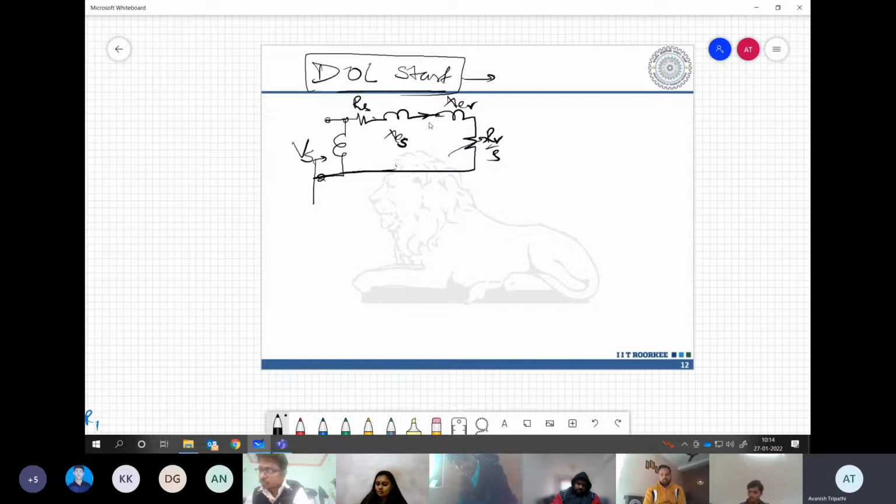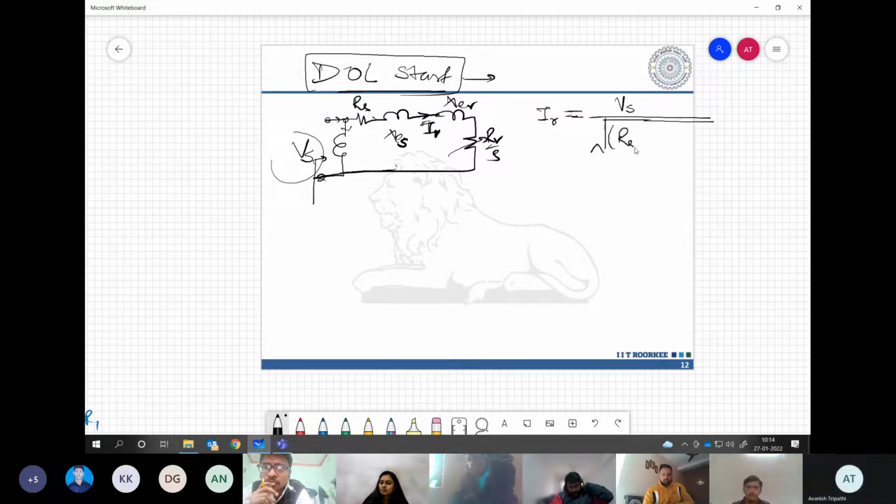Now the rotor current is more or less the stator current. That's what we know because the magnetizing current is only a small percentage, so we can ignore it. So more or less the rotor current is what we have as supply current. If we compute rotor current, which is almost equivalent to computing the actual current going into the motor, we will take this approximation, which we have done for the torque computation as well. So this is the expression we have got.